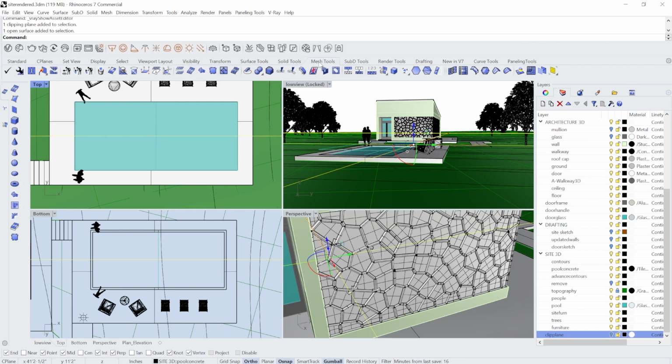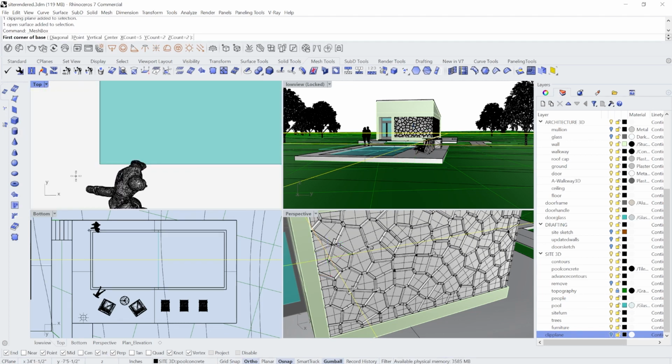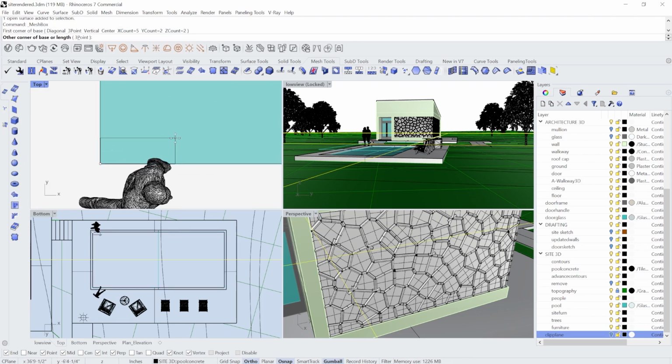And you see there are a few ways of doing a V-Ray light, with materials or just taking a mesh that's in the model. And I'm just going to make a mesh box. I'm going to make sure my settings aren't too much. Just 5, 2, and 2 for my count divisions. Actually, 12 by 2 by 2 should be fine. And I'm going to say 2 inches for my height.